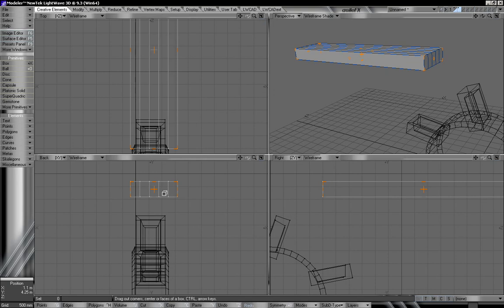And actually what I'll do is go ahead and add 2 more, and you'll see why that can end up being fairly important. Go ahead and select these 2 points. We'll switch to point mode. Select these. We can hit H on the keyboard to have stretch on. Just use the stretch tool to click and drag those fairly close to each other. T to move these points together, and H again with the other sets of points. And we just want to stretch these into each other. T to move that off to the side. And we're just going to kind of create a little slide here.